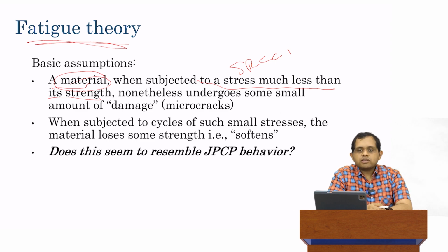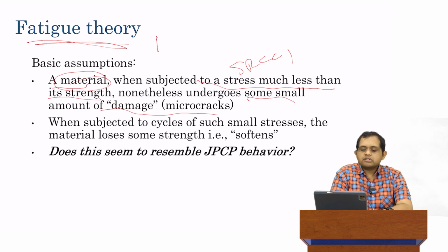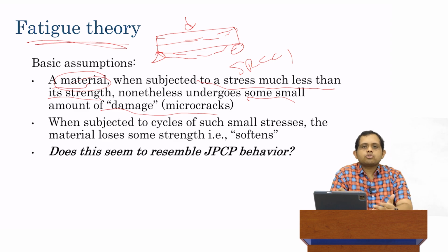Nonetheless, if it's much less than 1, you're not going to develop a crack. But nonetheless, it undergoes some small amount of damage, or what we call micro cracks. So for example, if we consider a simply supported beam which has been loaded, and we put a very small amount of loading, a crack is not going to form. You would think that, okay, we have perfect elastic behavior, that we load it and we'll get a deflection and a stress that's purely developed based on Euler-Bernoulli theory or any other elastic theory.